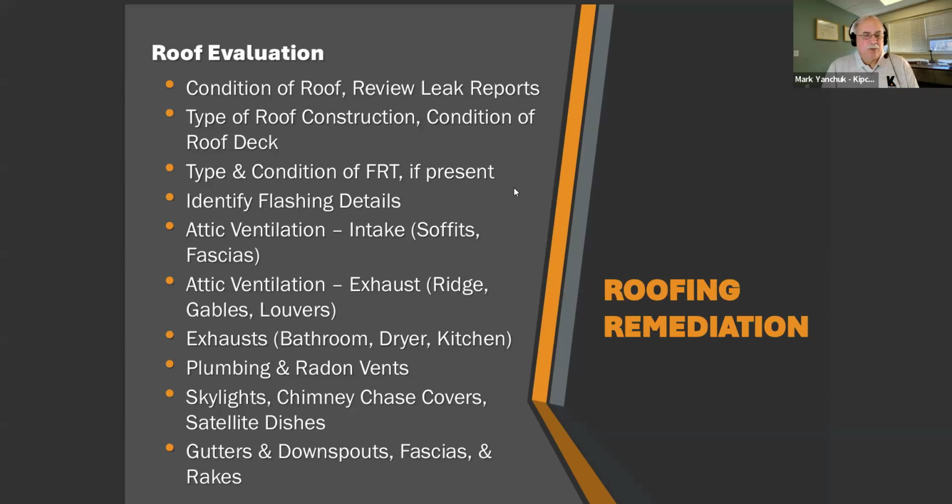Then you're going to have multiple roof penetrations. These are usually your sewer vents, your plumbing vents. And then you may have radon vents. These are easy to identify on the roof because the plumbing vents are usually schedule 40 pipe and the radon vents schedule 30 pipe. So they're easy to identify up on the roof. And then you have to specify the proper flashing for them. But it doesn't stop there.